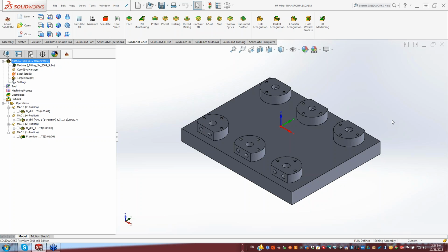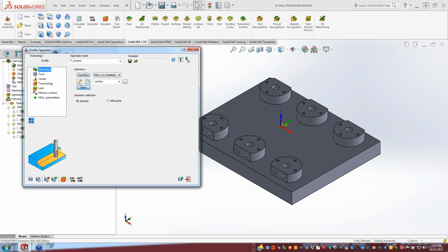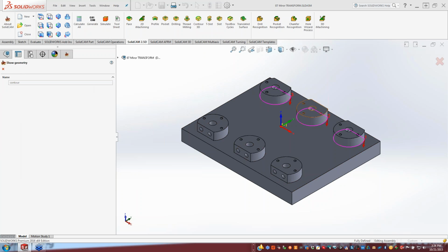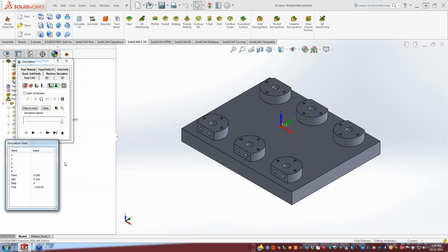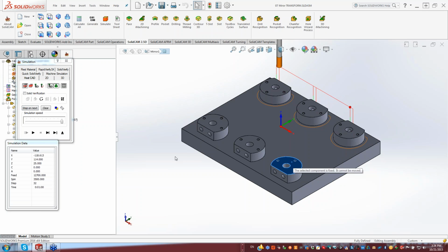Let's take a look at actually what I'm talking about right now. First of all, if I were to open up this particular operation over here, I'm machining out around these 3 parts over here. Okay? As you can see, it's going in my direction. It's going to go climb cutting as it did over there, and then go around the part, and then finish, and does the same on every single one of those parts. Okay. What I'd like to do is actually mirror these to get it working on these parts as well, but keep the same cutting direction.